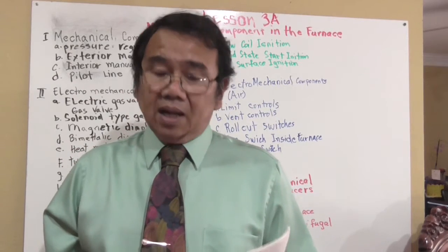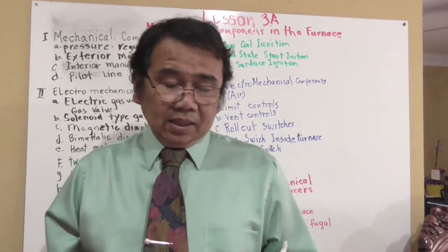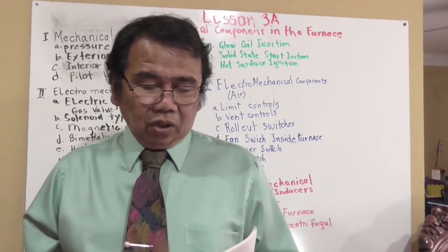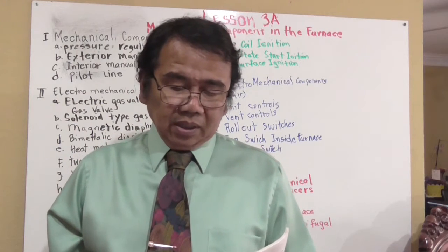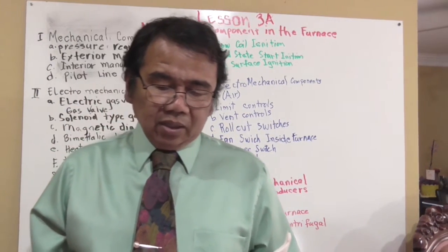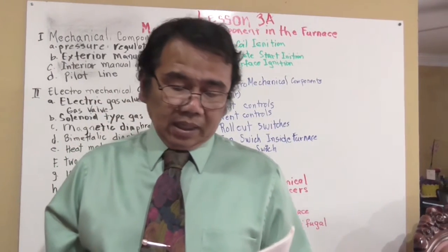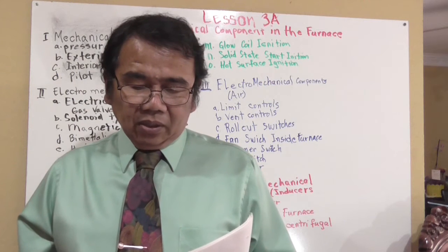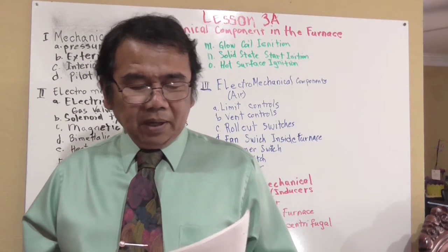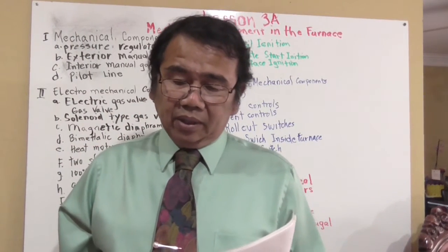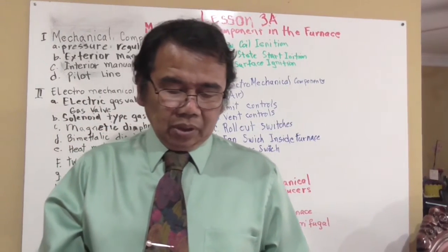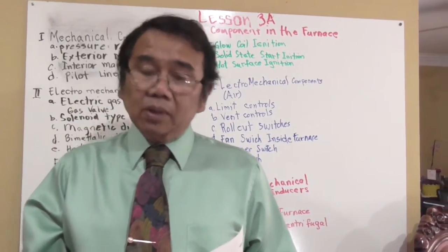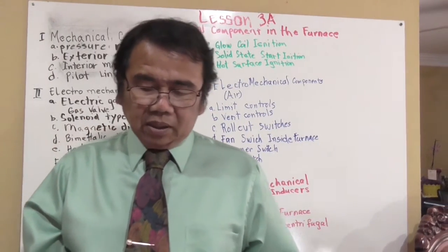The R and C terminals are internally connected to the transformer. The G terminal is internally connected to one side of the coil on the relay. The C terminal is also internally connected to the other side of the coil on the relay. The W and Y terminals are connected to nothing. They are merely connection points. When a fan center is used, all wires coming from the thermostat normally connect to the face of the fan center.